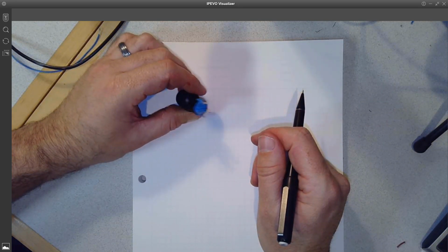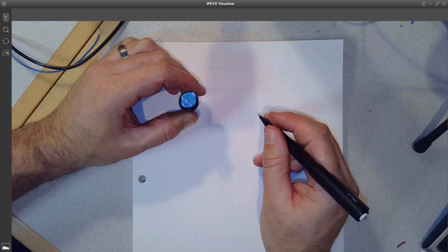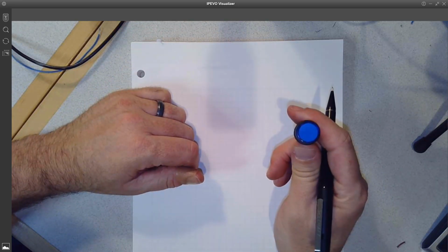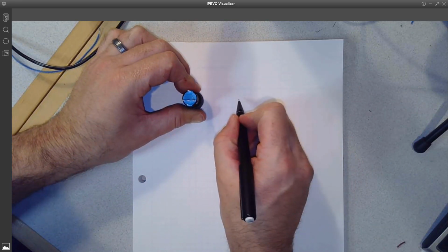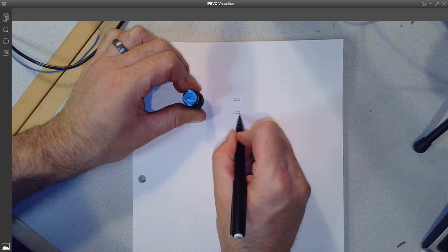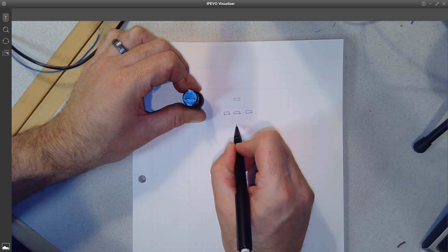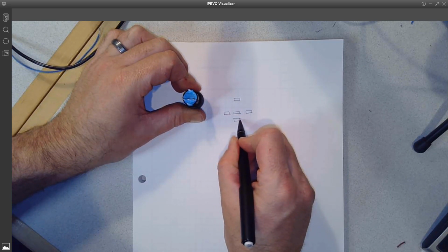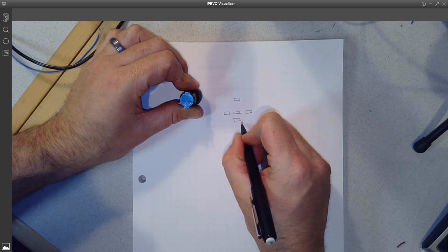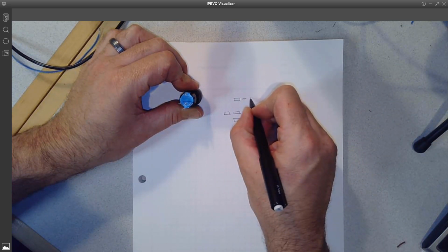Okay, so let's look at some of the details of the devices you're going to be using so that you can use a schematic that's consistent from each of your diagrams. So again, momentary illuminated push button. If we look at the back of it, it has a series of terminals, kind of a row of 3 that are the push button contacts, and then 2 perpendicular to those that are the lamp contacts. So looking at it, this one at the bottom is the positive for the LED to illuminate it, and this one up here is the negative for the LED.